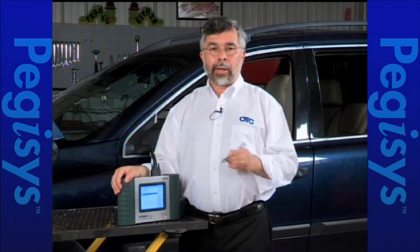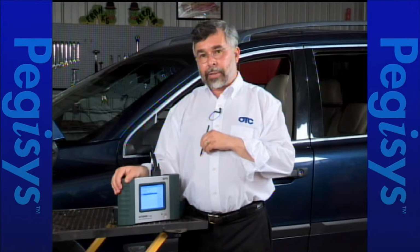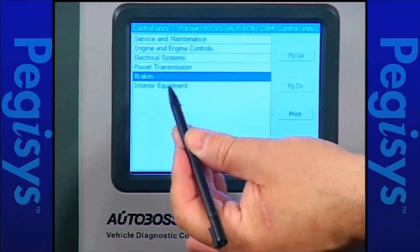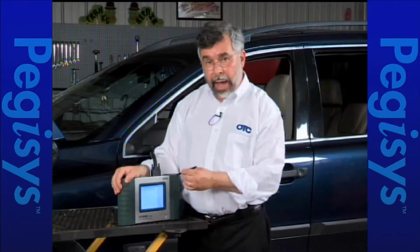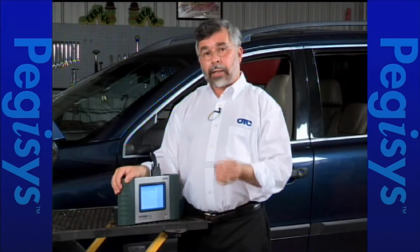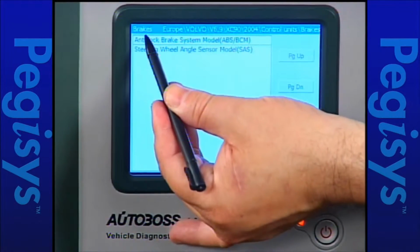Steering angle coding and yaw rate coding and lateral accelerometer are listed under anti-lock brakes. You would think it would be under steering angle, but it's not. So I'm going to go to the brakes module. When I tap on the brakes module, it will now list on the top anti-lock brakes and steering angle. However, once again, steering angle and yaw rate sensor and accelerometer and lateral accelerometer are all listed under anti-lock brakes. So I'll tap on anti-lock brake.